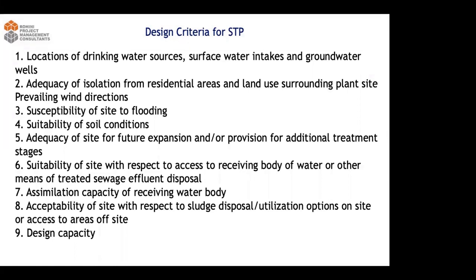Then the suitability of the site with respect to access to the receiving body of water or any other treated sewage effluent disposal. Okay, so these points are the basis on which we can size the STP and say that yes, we will be able to locate the STP based on the topography or any other parameters that we look into.